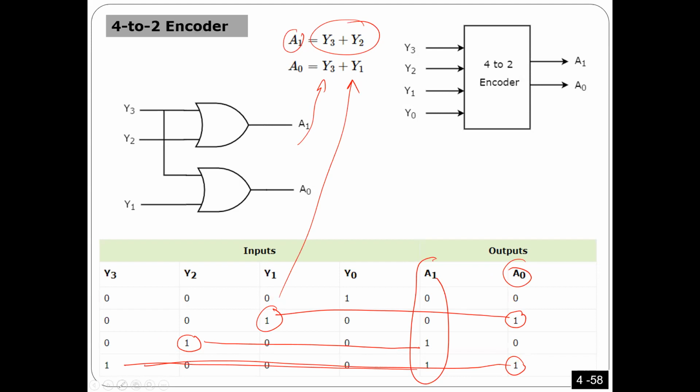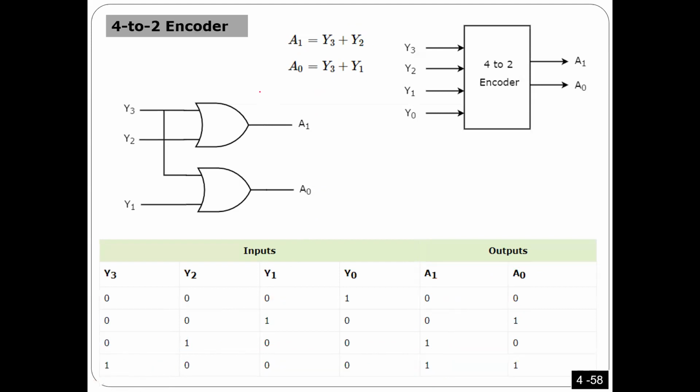So I am done. So this is actually the encoder. So the encoder looks something like that. It has 3 inputs. Sorry, it should have four inputs, including Y0, but actually Y0, I'm not going to use this input. So this input is not included here, and still the circuit is going to work. Okay. So this is how the encoder looks. So if any one of these is 1, you are going to get the correct output here. Any questions?